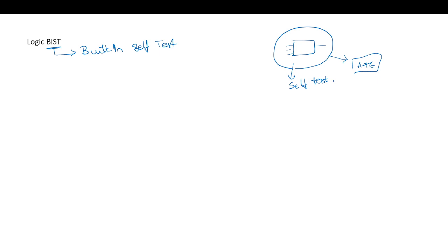Traditional test techniques become quite expensive. These are some of the problems in today's semiconductor testing; they no longer provide sufficiently high fault coverage. Why do we need built-in self-test? We need it for mission-critical applications.